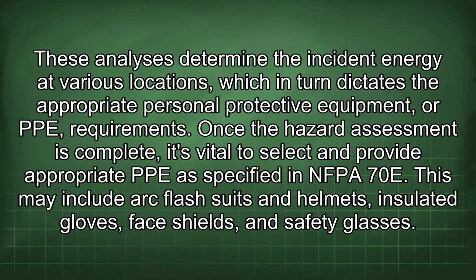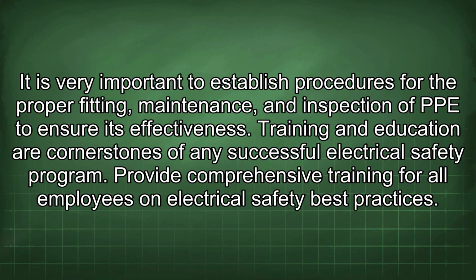These analyses determine the incident energy of various locations, which in turn dictates the appropriate personal protective equipment, or PPE, requirements. Once the hazard assessment is complete, it's vital to select and provide appropriate PPE as specified in NFPA 70. This may include arc flash suits and helmets, insulated gloves, face shields, and safety glasses. It is very important to establish procedures for the proper fitting, maintenance, and inspection of PPE to ensure its effectiveness.